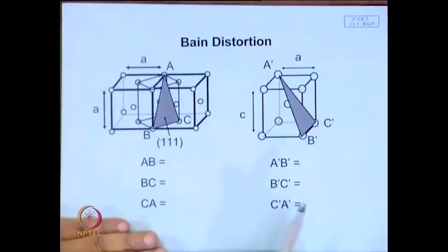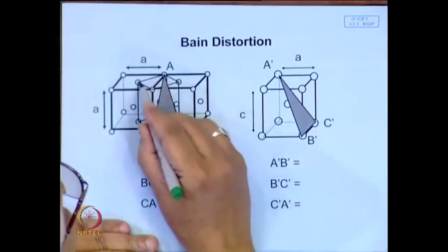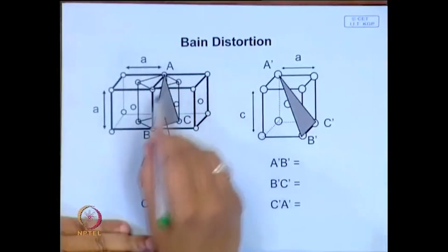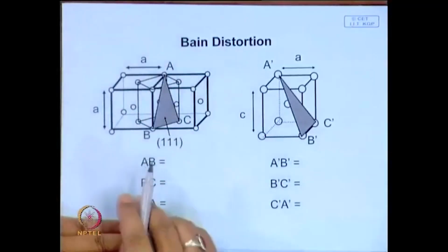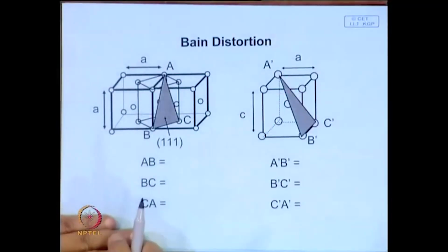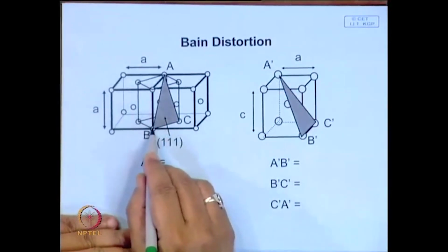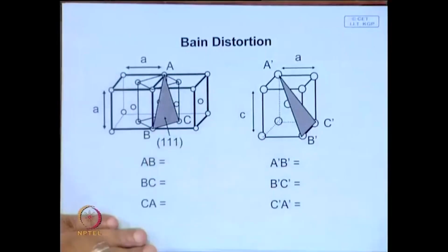Now, if this type of transformation takes place, then there are set crystallographic restrictions which must be followed. And look at this, this is shown in this next slide. Here, look at this, this is the cell in the previous diagram, which gets converted into a body centered structure. Now, look at the correspondences of different planes and directions in this case.